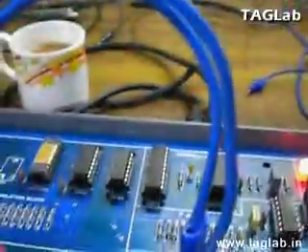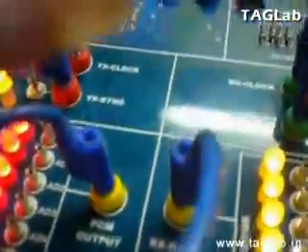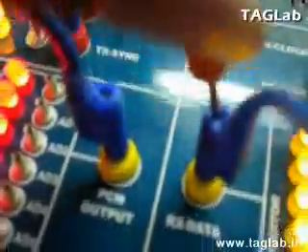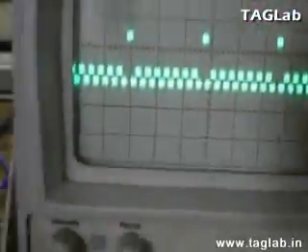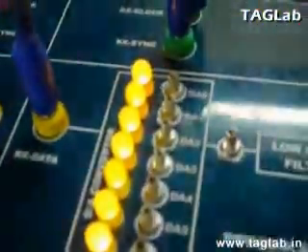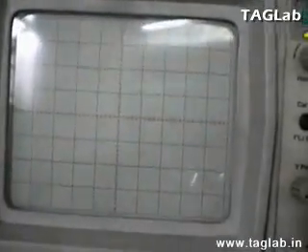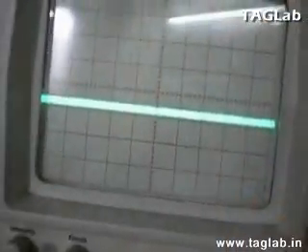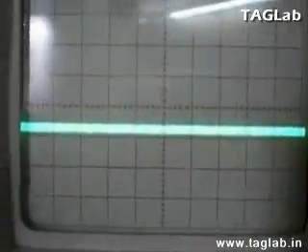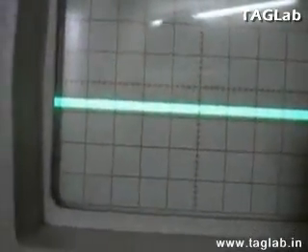Now, to check the demodulation, first verify whether the PCM output is given at the transmitter data. The output is same. Hence the demodulation block has received the PCM data, and at the output we check, we could see our DC signal back at the same position.